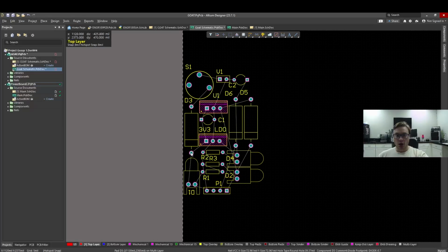This is where our VCC net basically starts. Goes input for 3.3, decoupling capacitor, and then we've got the 5-volt LDO. These are our ground pins all through there. 3.3 volt output. We've got our 5-volt output. Protection diodes for both of those voltage lines. All of our indicator LEDs and resistors down here. Pin header to connect to another board.